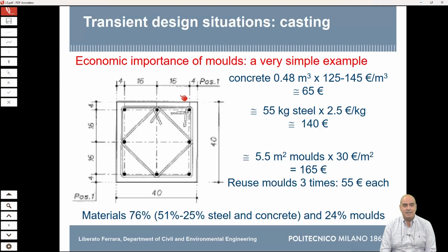Yeah, one thing is that because when you strip the molds, you can have something. So the quality of your finishing will not be good. And this is also because even if we use a timber, which is exactly mold timber, there will always be some infiltration of the slurry of cement inside that. So after a certain point, you cannot use that mold. This is also another important thing, because those molds are timber but cannot be burned because they contain cement, which is a toxic waste. So you have to dispose them with a special procedure.